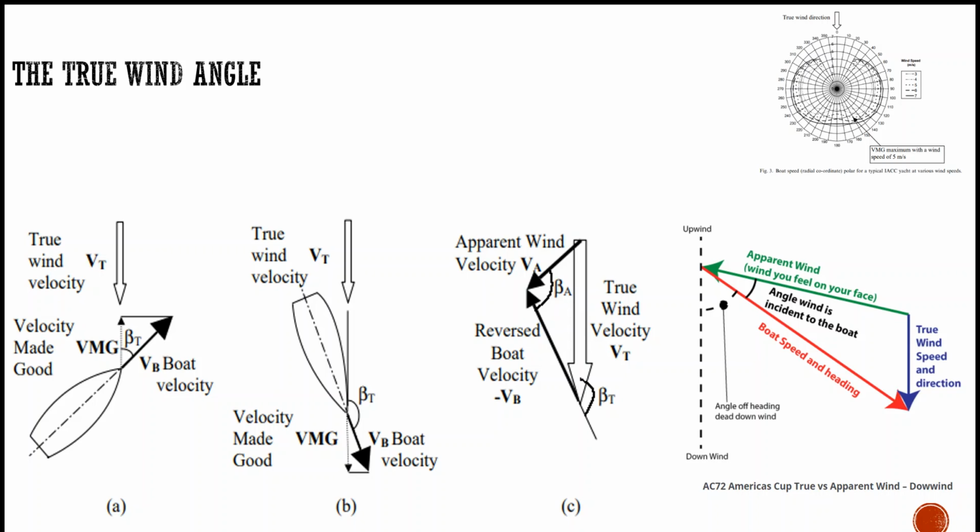As a result, the thrust is small and the achievable boat speed is low. However, if a yacht sailed with lower true wind angles, then the vector sum of the true wind and the boat velocity results in higher apparent wind speeds and hence greater thrust and boat speed.